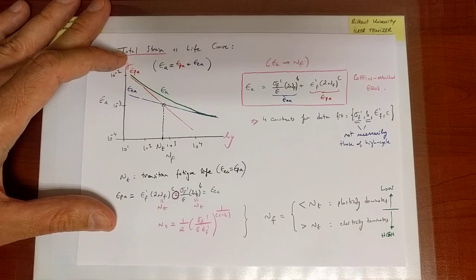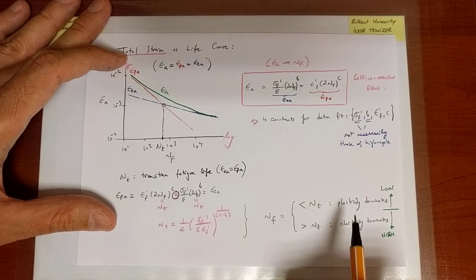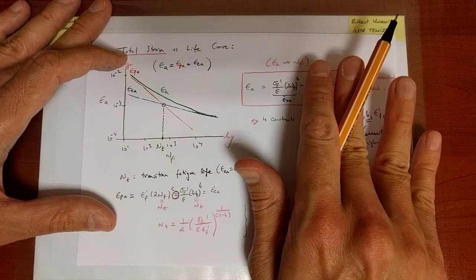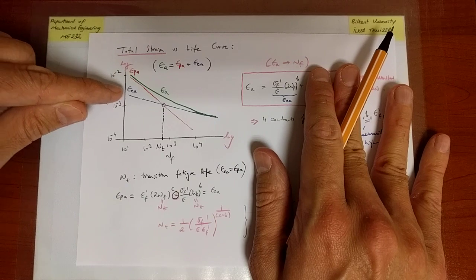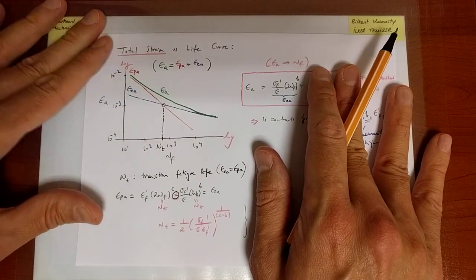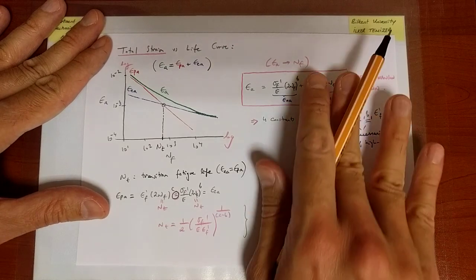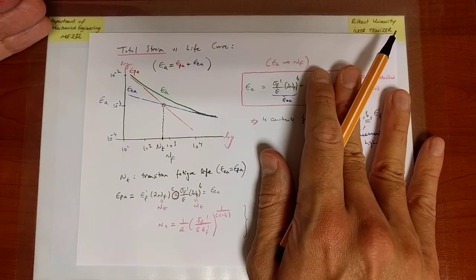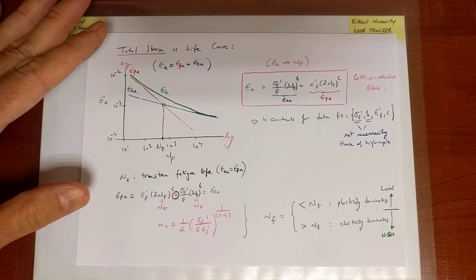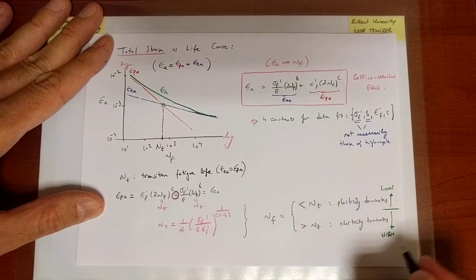Okay, because for high cycle fatigue, the motivation we stated is now implicitly appearing here. If we want to go up to relatively high cycles, plasticity has to be negligible, because we observe that high cycles are associated with small plasticity, and we end up with the Basquin equation, which is the stress-based approach. Hence we had already stated that the stress-based approach is for high cycle fatigue where there is little or no plasticity. And that's what we are now seeing here.